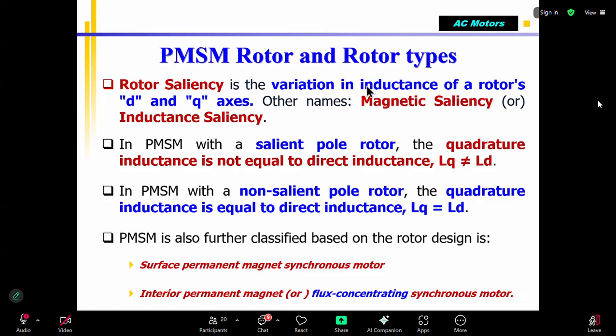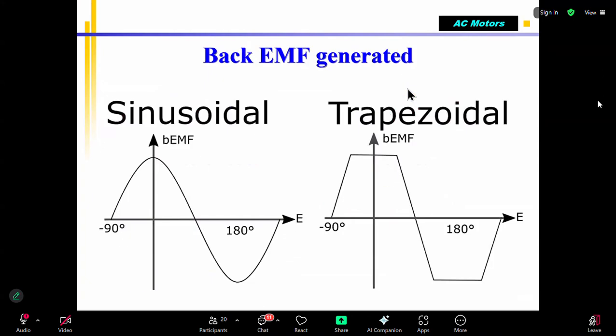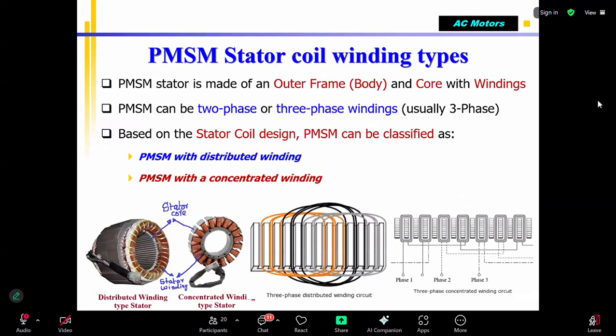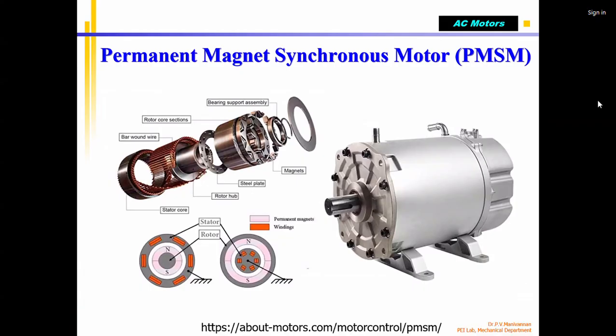Okay, shall we start? We can start. We were talking about the permanent magnet synchronous motor, a type of AC motor. Its construction, yesterday we just started, correct? Very simple. It is a synchronous motor, but the rotor is a permanent magnet. So a lot of complications are reduced: supplying DC power, slip ring, complicated mechanical weight reduction. All these things are advantages.